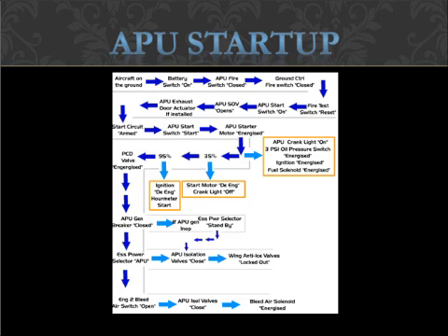The other type of APU uses a generator to supply electricity for main engine start. In this case, the starter is an accessory drive motor or a generator that spools up the main engine to start and then generates power after reaching light-off.